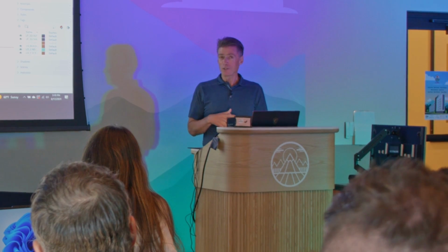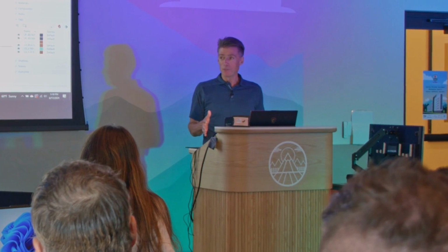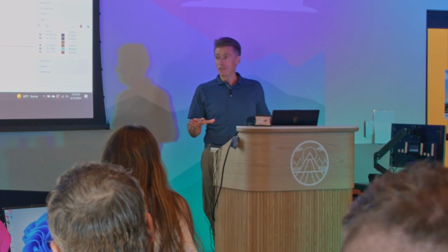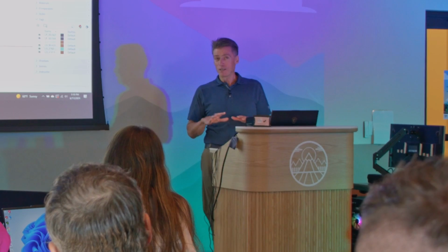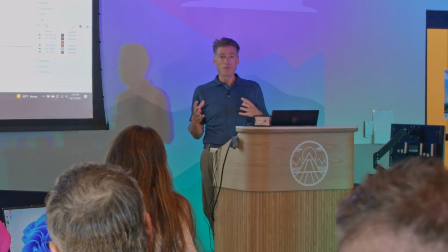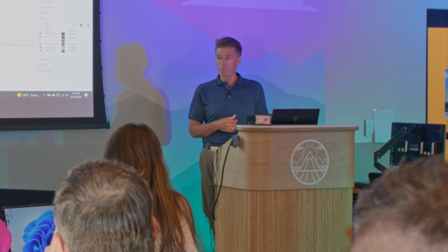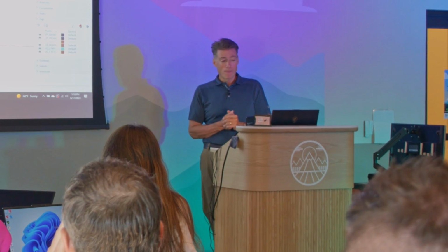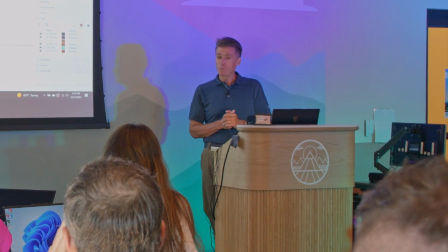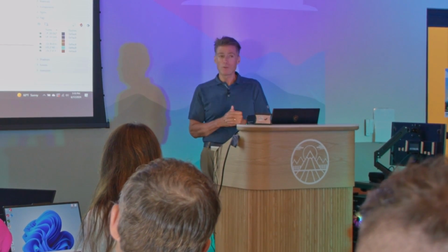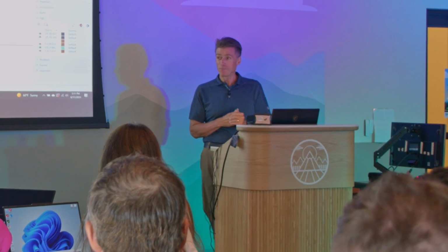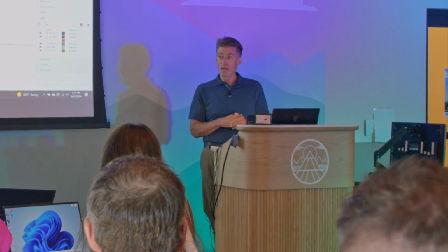Because by the time I'm finished with my design development, I've already got the site plans, floor plans, elevations, roof plans, sections at CD level. And then when I get to construction documents, it's really adding more notation to those drawings, then creating the other ones like the reflected ceiling plans, MPE, details, and schedules. So I always kick myself because I end up spending definitely more than 50% of my fee, I think, in schematic.